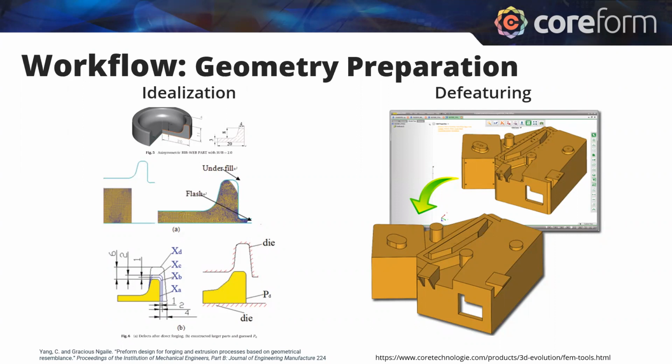So I don't need to waste degrees of freedom and computational expense on other parts of my geometry. I'm going to defeature those, keeping general forces so that I can trust I'm getting accurate results in my fillet, which I won't defeature. So this is where the practicality of simulation really comes in.